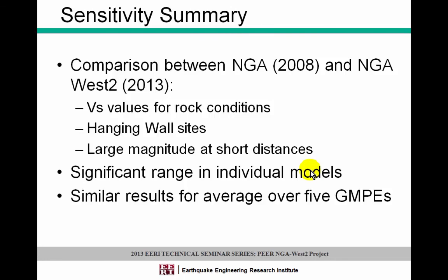And I think that in going forward, as I started with in my opening presentation here, people ask me all the time, how's that going to impact my project using the new models? I think these are the types of things that one needs to consider, especially if it comes down to the point of developing weights, whether you want to equally weight them or come up with non-equal weights for the project, just so you can understand how the differences have changed in the ground motion models before it goes all the way into, say, the hazard or all the way into the design spectrum.